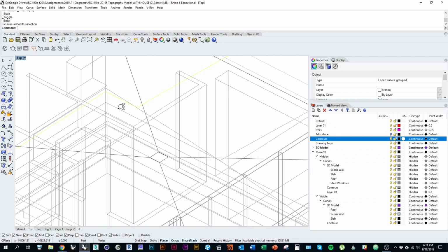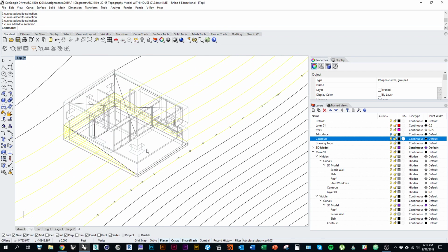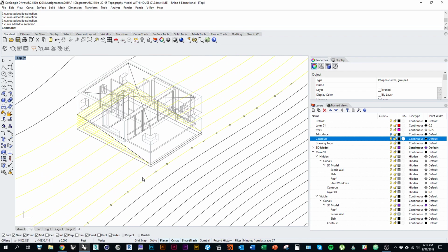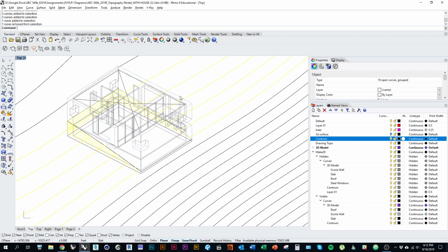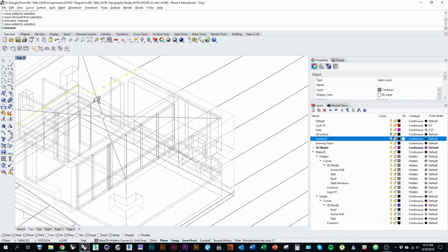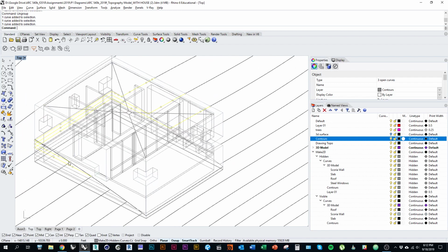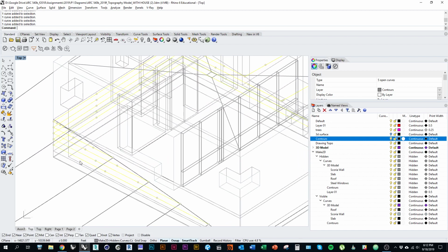So first of all, I'm going to delete all the hidden contour lines that are wrapping around the back of my house over here, because I think those are distracting. Because we chose the option group output, even though these lines might be on different layers and might be separated already, we need to use ungroup just to get at those particular ones back here. And then it looks like we also need to explode them, because I still want this part of the line here behind the house. I just don't want the part that wraps around where the house is sunken in. Let me select all these lines and explode them.